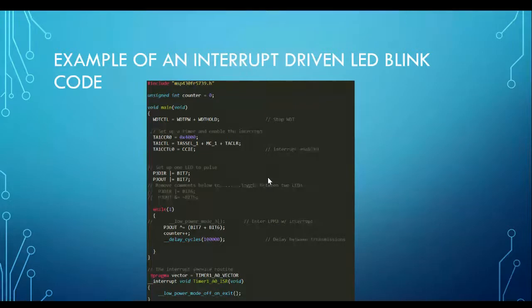Take this example. If you can see this part here, these are timer settings. You don't have to go so far. Basically, these are just timer settings. Now understand this. What does it mean? That means bit 7 of port 3 is being set, so you don't disturb the other bits.